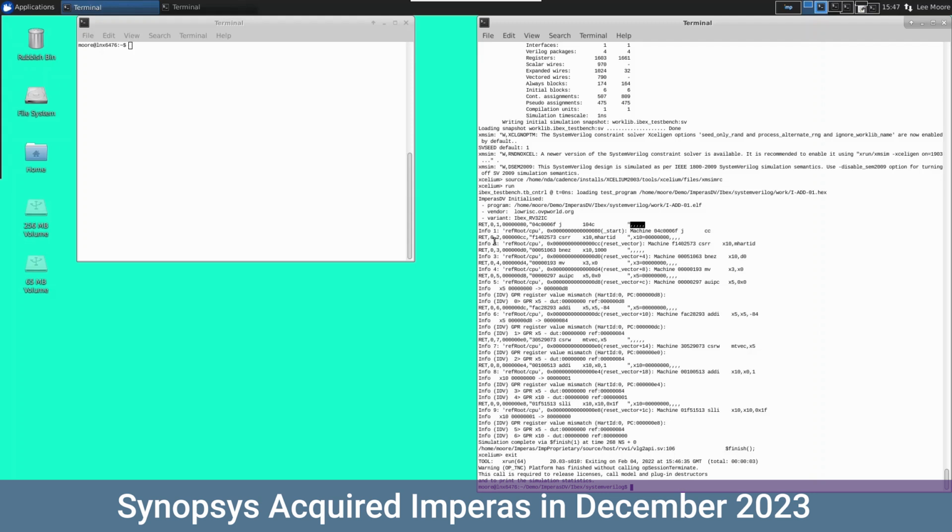The next instruction to be executed is a CSR read from the hart ID into X10, and so it reports that we've got a change on X10. It just so happens that that's a write, and it's writing in the value 0. And when we do the same operation on our model, it compares, because the default value is 0 at that point. Now, where we get the difference is more interesting.